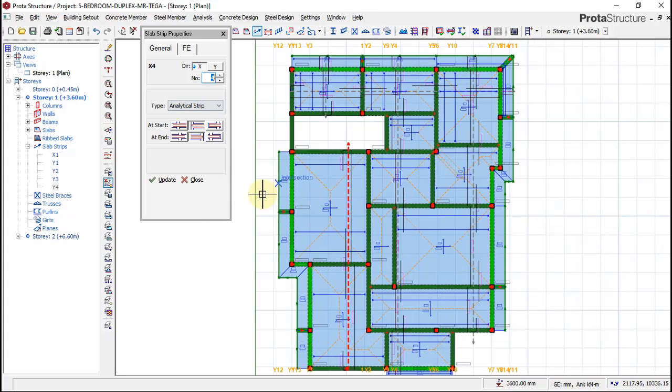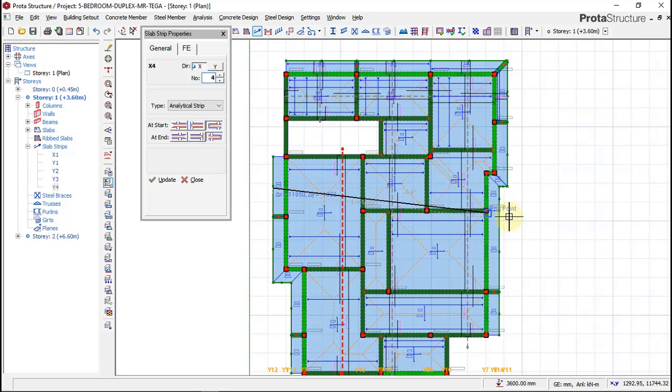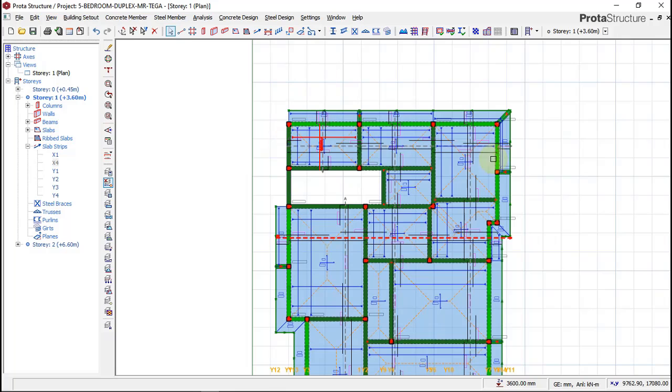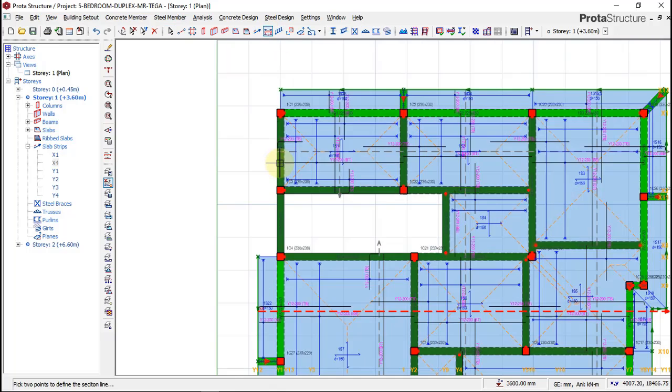Okay, now we do the x-axis right now. The x-axis of this slab, these both ends have cantilever. So I'll quickly pick cantilever and then go across and then click again. So now to cut your slab section through this slab, to see the slab section, you go to floor plan section, click on that icon.